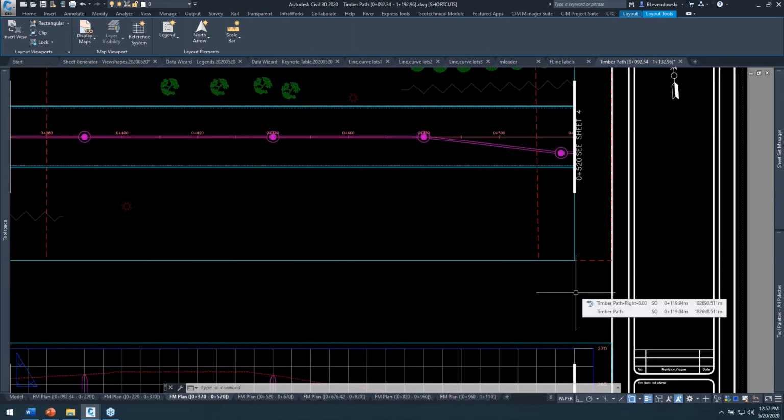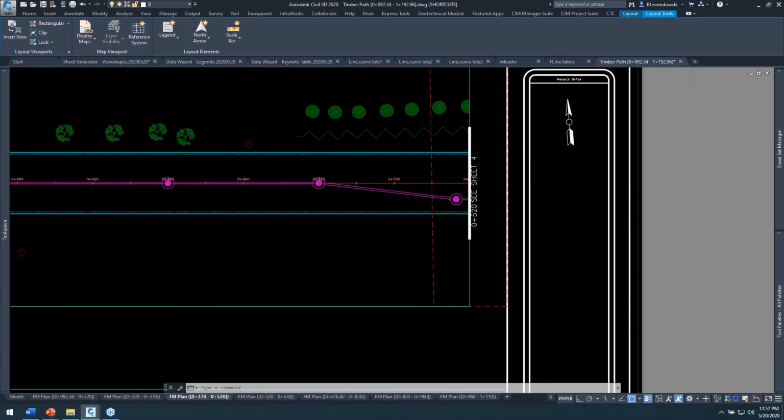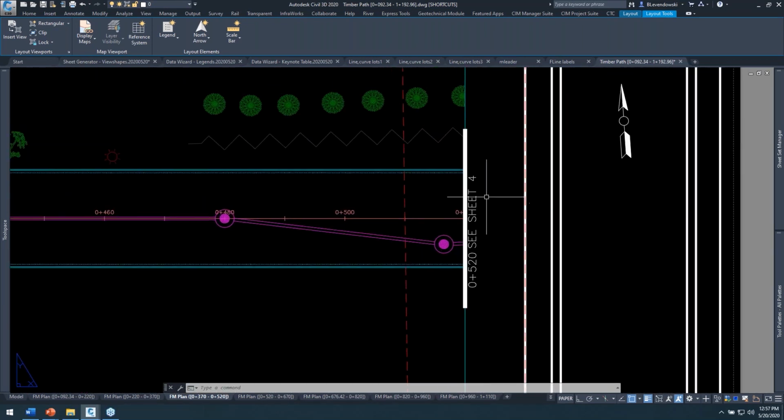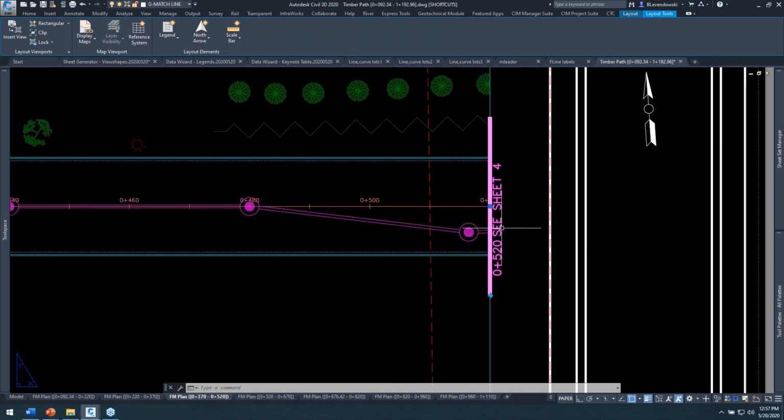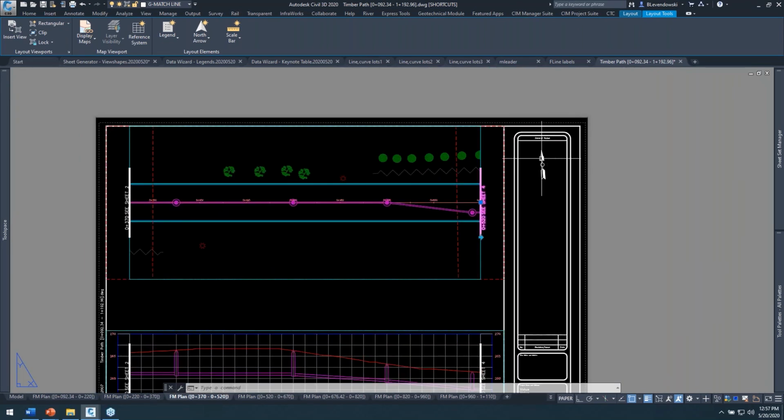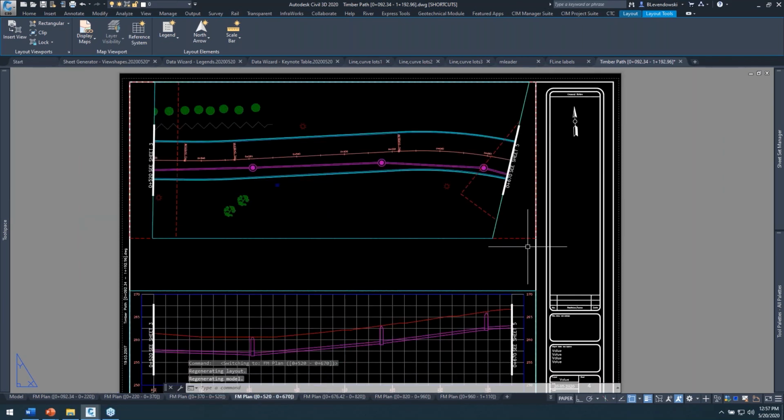And we're not making any proprietary objects. It's all working on native Civil 3D and AutoCAD objects. Here's the plan match lines. Now what this looks like, again, this is just a block. You can use different line types, different text, whatever you want. But the point is that it populates sheet set fields in here. So the stationing, the sheet number, if you want the sheet name to show up in here, it'll do that as well. It rotates the north arrow for you. It's naming all these tabs down here, okay? Doing a lot of work for you.